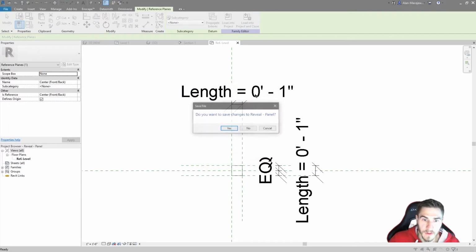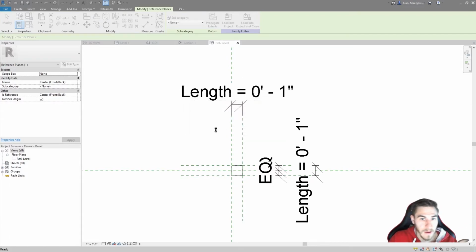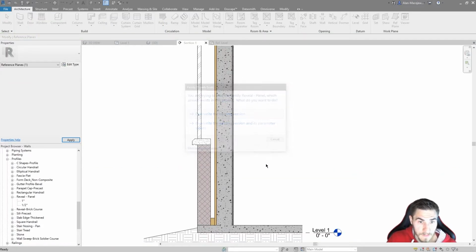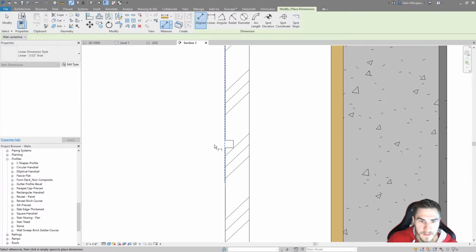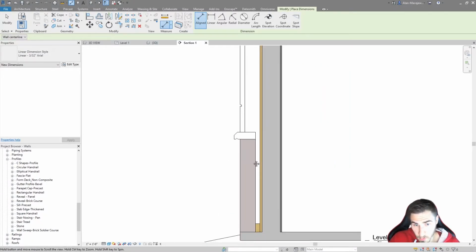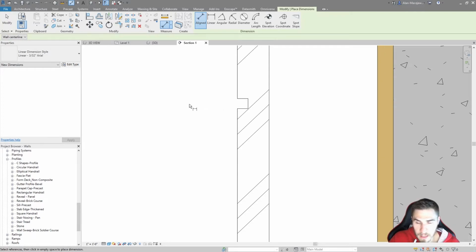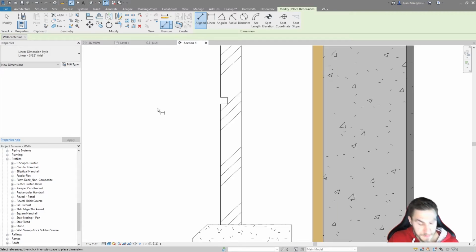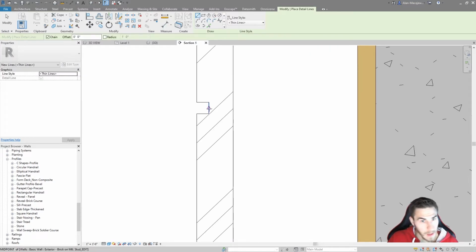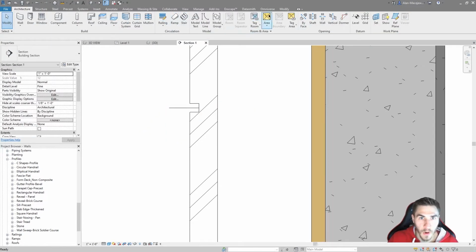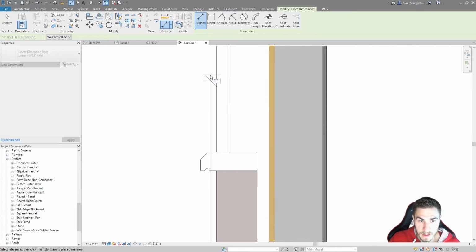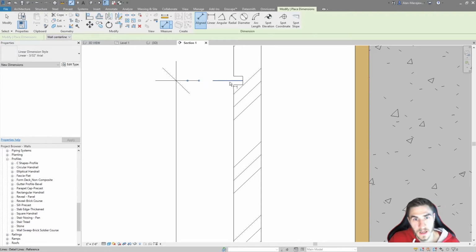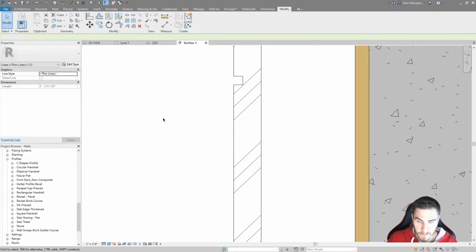Cool. We'll go ahead and load this in, save this, and now basically everything's going to move down and our dimensions are going to work out really well. So here we go. Go back to our dimensions from our level. And because the profile is baked into the wall, we unfortunately don't have the option of using that actual origin point or origin plane as a way of dimensioning, which I have a problem with, and that's just because it's within the wall. But I'm going to draw that line just so we can dimension to it, and I can show you exactly where that 4 feet is hitting. So there's my 4 feet, and so that dimension now is accurately placed within the center of that reveal. Okay, so that's good to know.